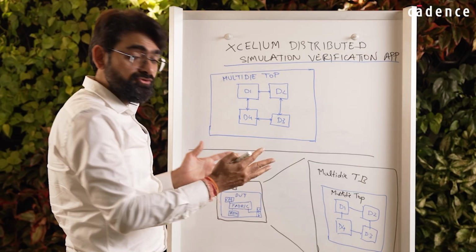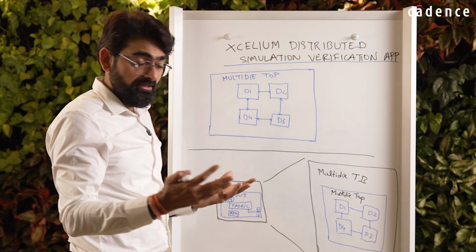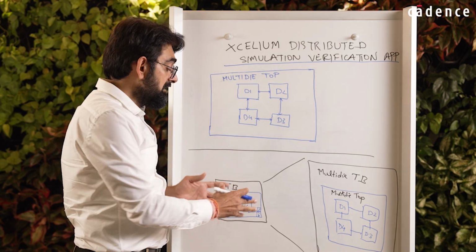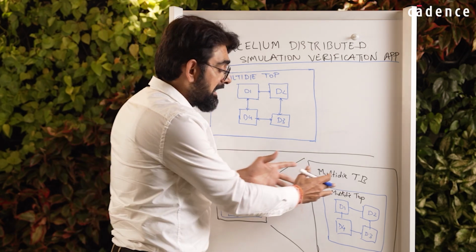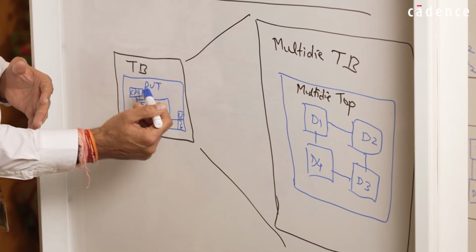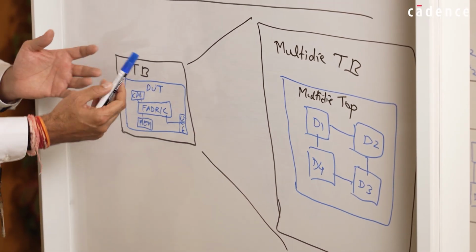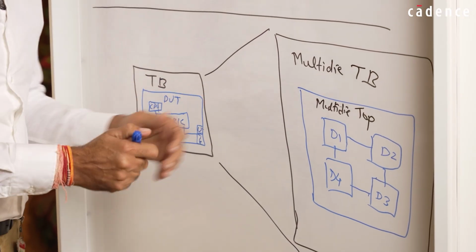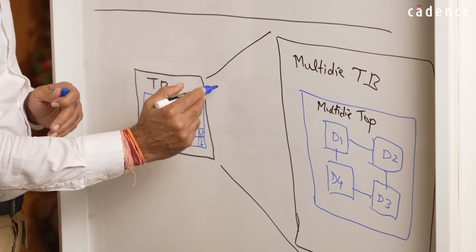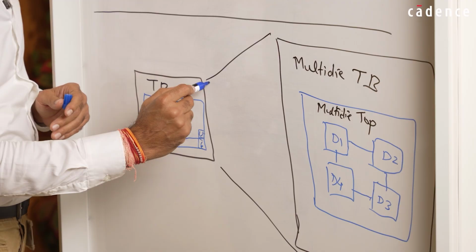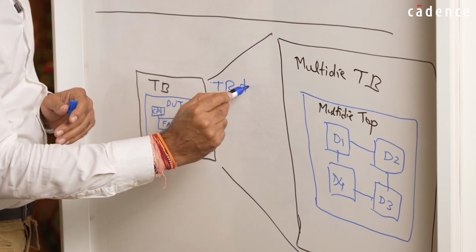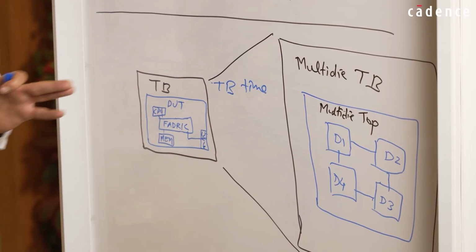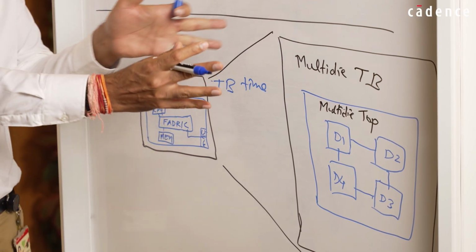That's how you typically do SoC verification, or any verification for that matter. And then you extend that. So if you go from 1 die to 2, the number of agents in your UVM test bench increases by that many X. So it is basically your test bench time. This is one challenge, going from single die to multi-die.